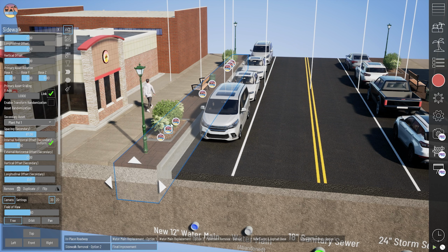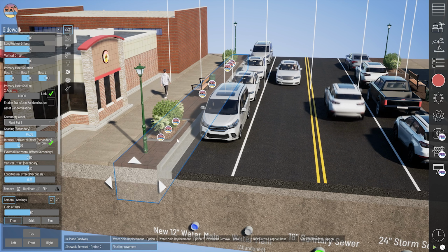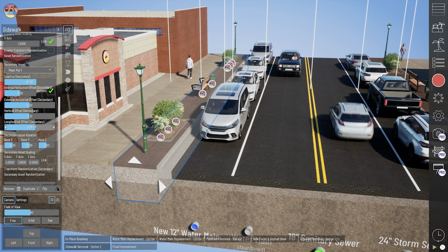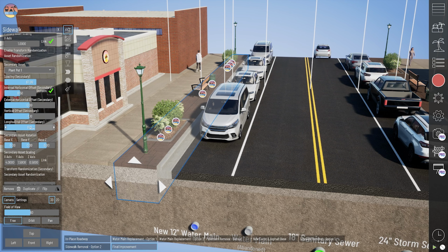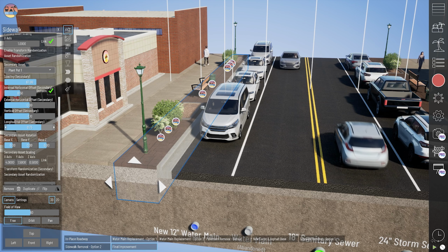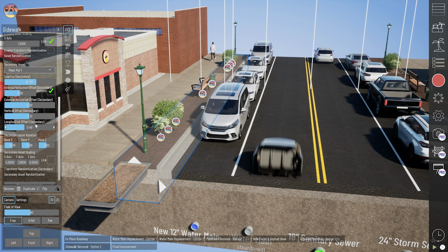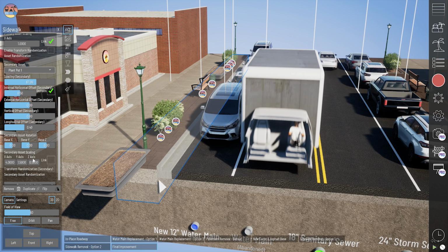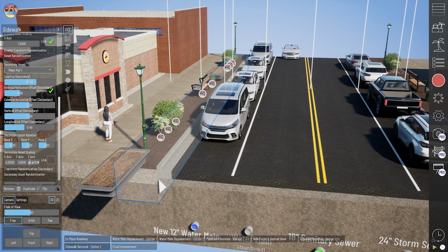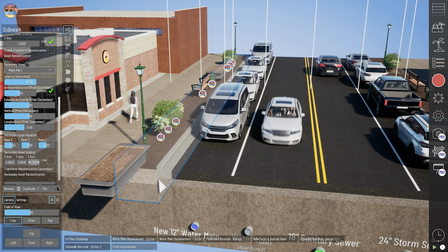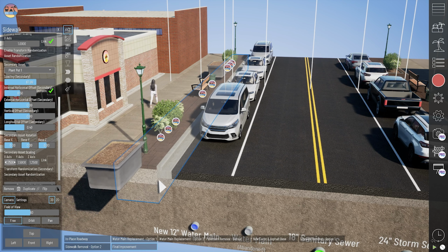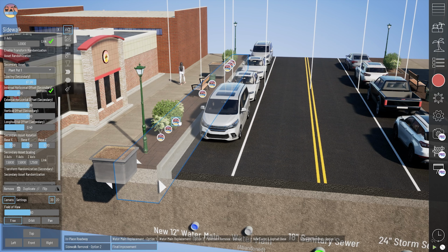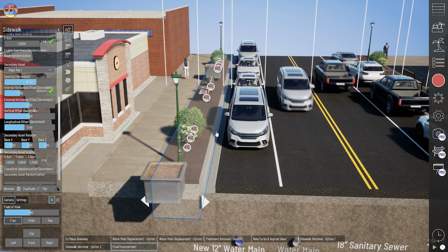One thing I want to highlight here in this section is these planters that look like in-ground planters are actually just a stretched out and lowered plant pot. So if I pull this section up, I'll pull it forward so you can see it. It is just lowered, so I've lowered my vertical offset, and then I've stretched out in the X direction and shrunk in the Z direction, basically just our original potted plant to put that below the planters here to show an in-ground planter.